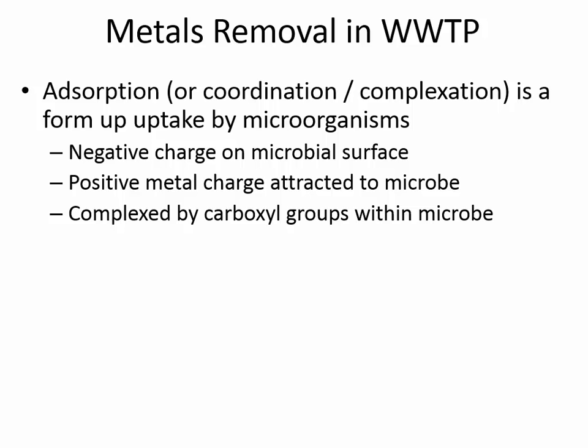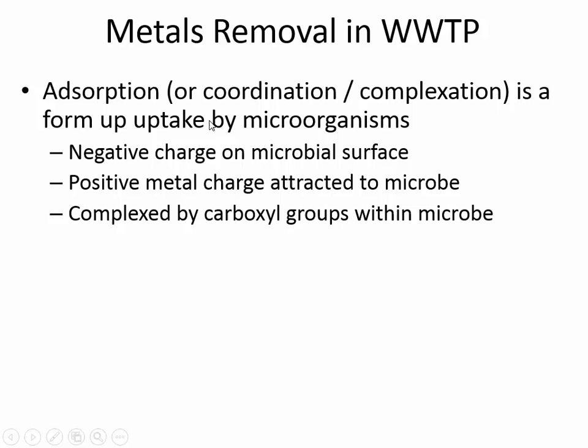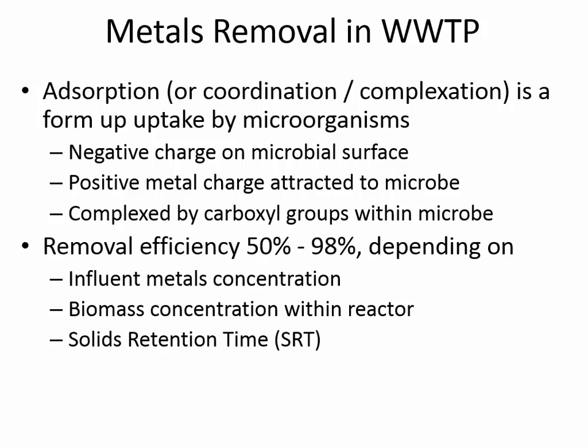And so the way that they are taking them up is that sometimes the metals will have a positive charge, depending on if it's an elemental or if it's complexed with an anion. And so if the metal is dissolved and has a positive charge, microbial surfaces often have a negative charge on the outside surface, and so the metal will either be absorbed by the bacteria or just sort of attracted to the bacterial surface and then can precipitate out or can be concentrated through the clarifier.